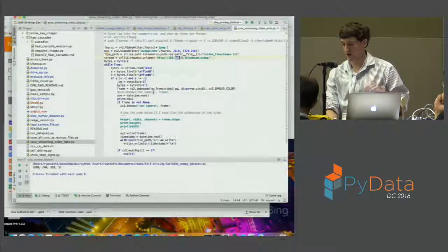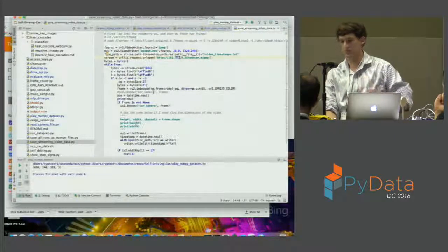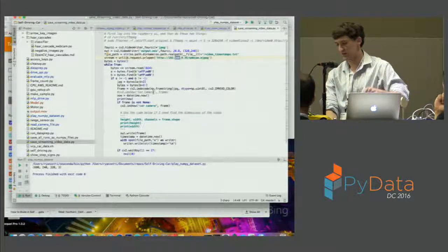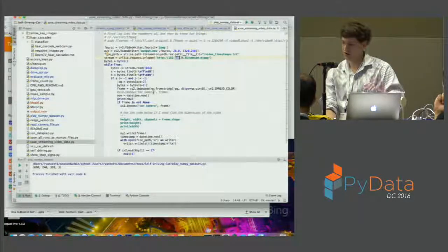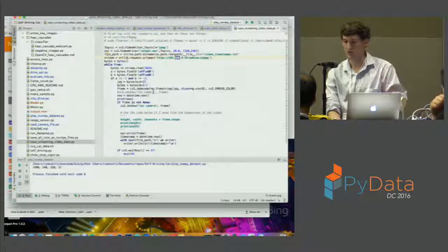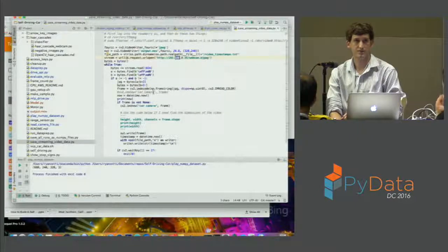So if I hit up, because I'm not really ever stopping the car, I assume that I'm going to keep going forward until I get my next delta, which is left or right. And then basically I match up the timestamps from the video with timestamps from the commands to know how to assign which commands to which video frame. Yeah, that was a pretty complicated part.